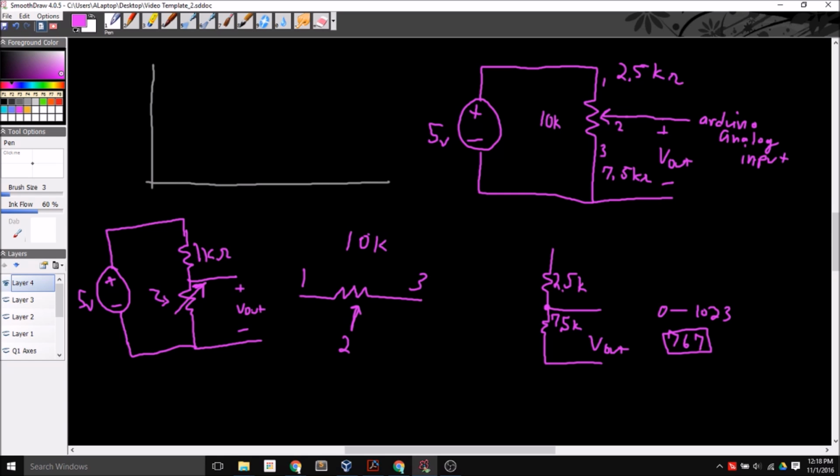So you can put your hand over it to make a shadow and see if that changes the value, and you can actually calculate the number of milliseconds that you expect it to go on and off based on the resistance of that photocell. So that should be it for analog inputs. The next video will discuss analog outputs, which are a pretty useful tool as well.